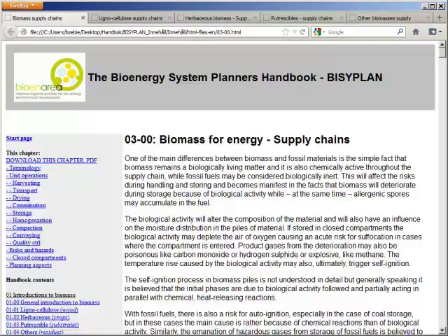For cold-pressed oils and also for pyrolysis oil, it must also be remembered that the oil is by no means pure. It will contain a lot of different hydrocarbons, some of which may be easily oxidized and basically may solidify, partly in contact with oxygen, but partly also because temperature is low.